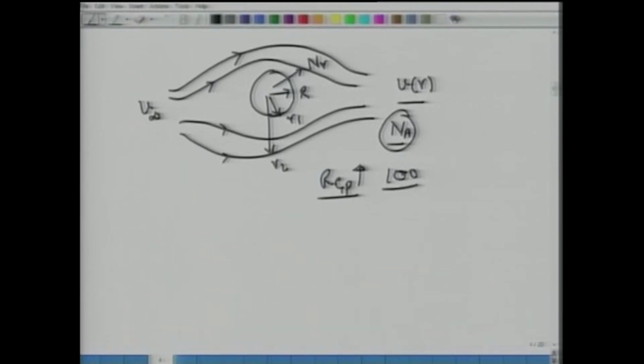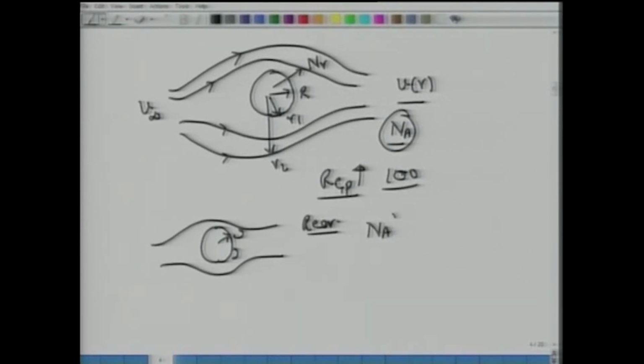If it's very large, say 100, then there is uncertainty in the velocity profile. And if you recall from your aerodynamics, we will have cases of boundary layer separation, etc., or the eddies which are formed at the rear end, in which case predicting the diffusion flux in terms of your bulk transport and diffusion flux involves a lot of error. In these cases, it's possible to define a mass transfer coefficient quantity and to say that